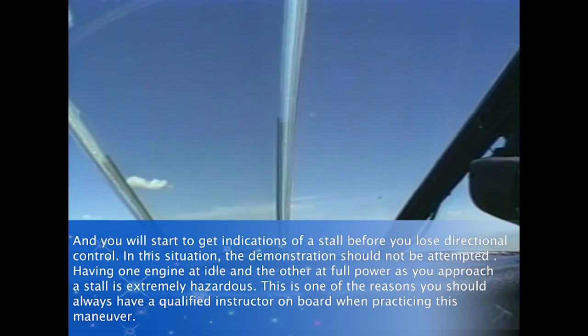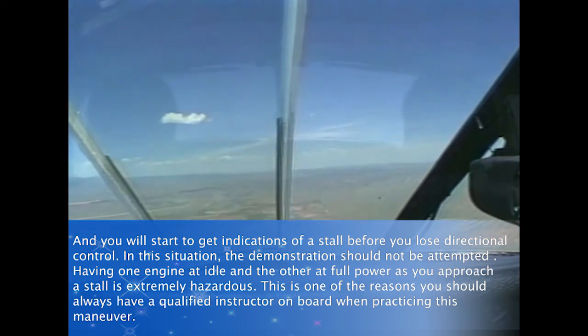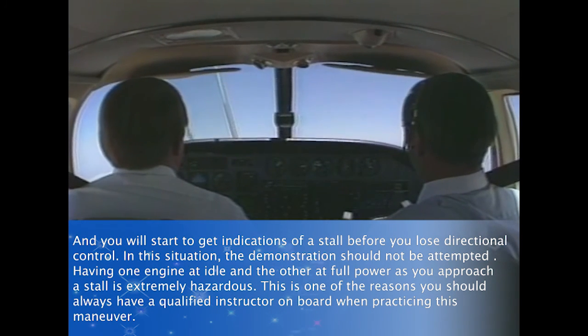Having one engine at idle and the other at full power as you approach a stall is extremely hazardous. This is one of the reasons you should always have a qualified instructor on board when practicing this maneuver.